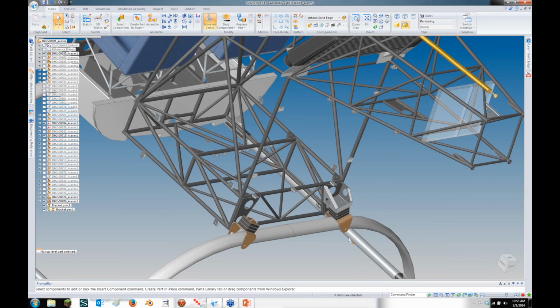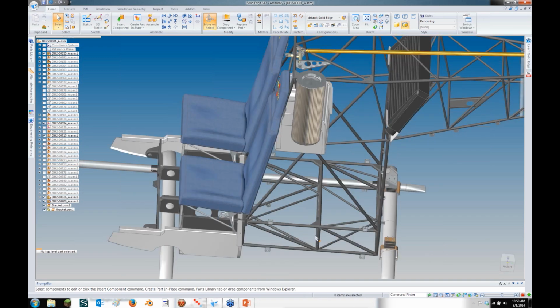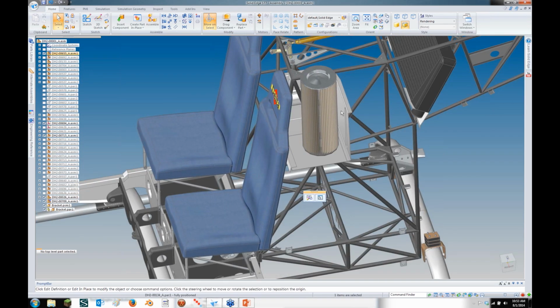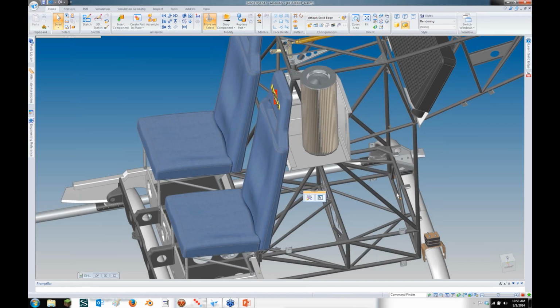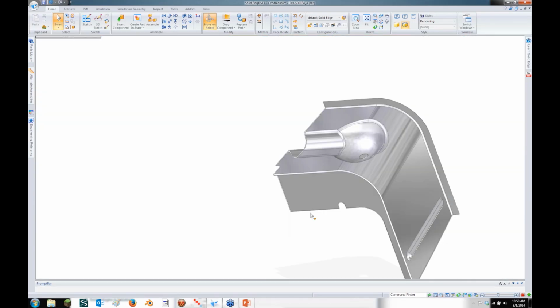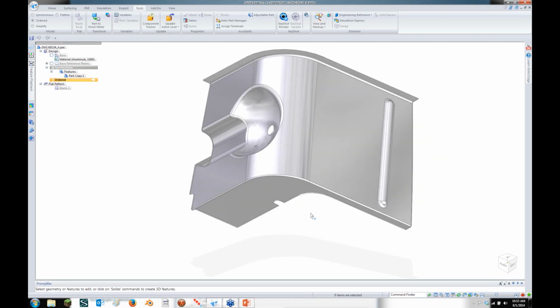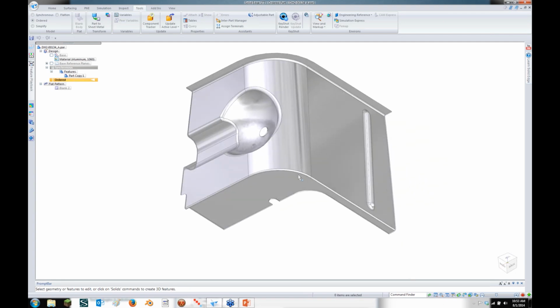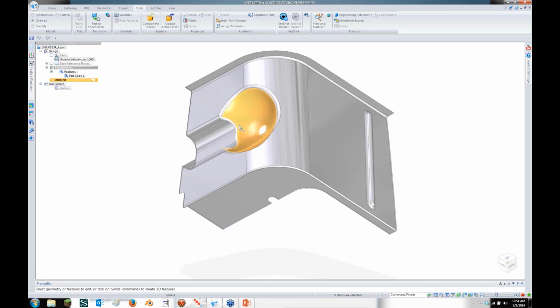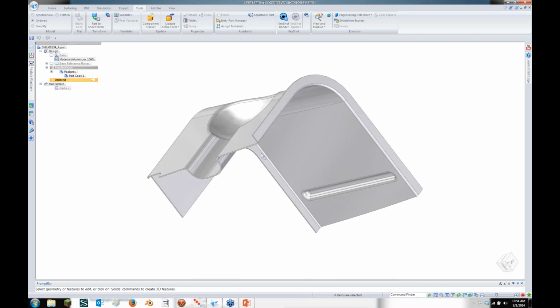The next thing we're going to look at, again, is what I was talking about, the flat blanks parts. In this one, it's the actual sheet metal part, and I can guarantee you, I can convert that into sheet metal, but I wouldn't get all these features to flatten for sure. The actual stiffening bead and this fairly deep draw dimple.